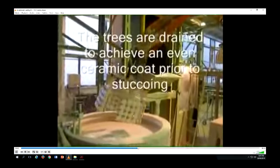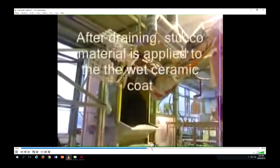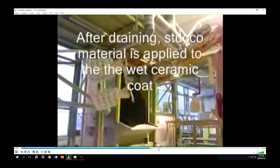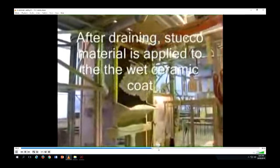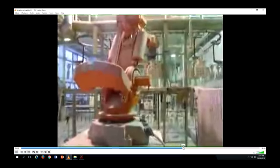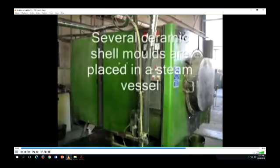This is the ceramic mold. Again, this itself has a process to give you a good quality mold that doesn't break easily. And you put it in the oven. Here's another layer coat. And then after the ceramic is formed, now they dewax it.